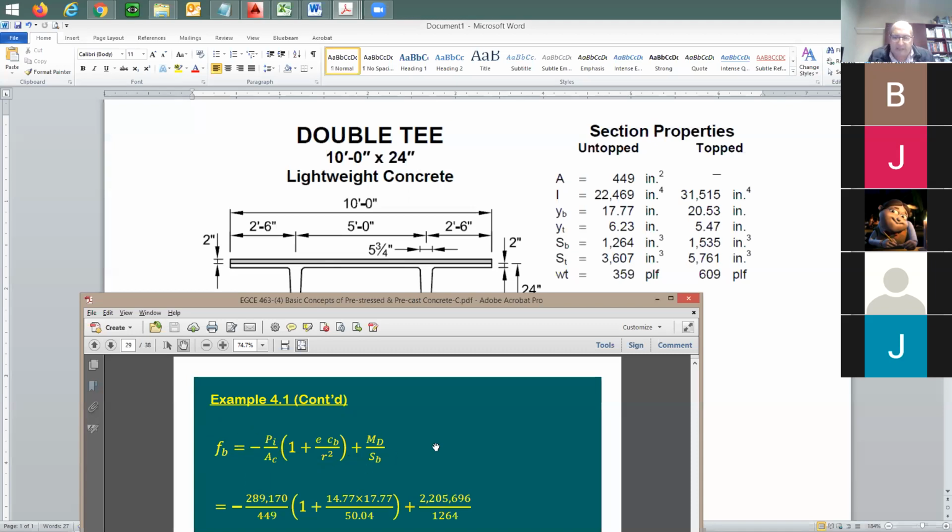And my question, I'm going to be very specific here. I'm going to say, once you move the double T, and before you apply the live load and the concrete topping, find out the stresses. In this case, you're going to say here, PE, and it's going to be only M dead load, correct? You agree on this? We're good? Yeah. All right. Now we have the stresses top and bottom.